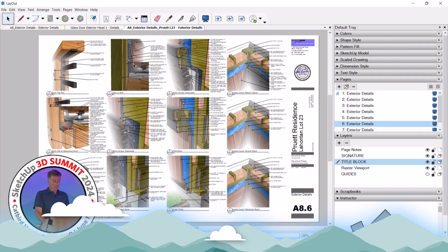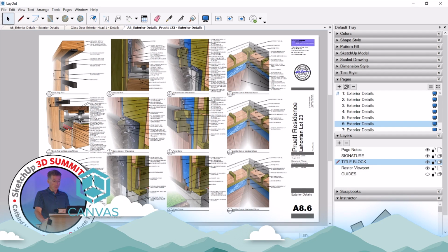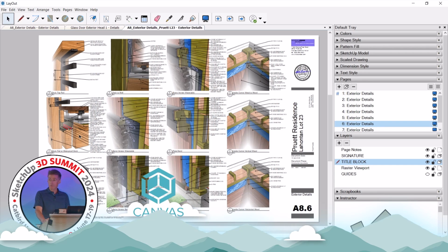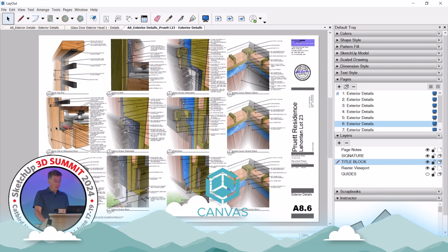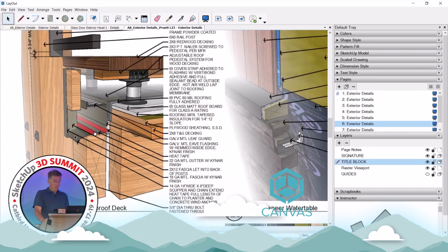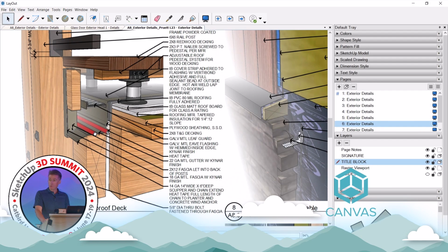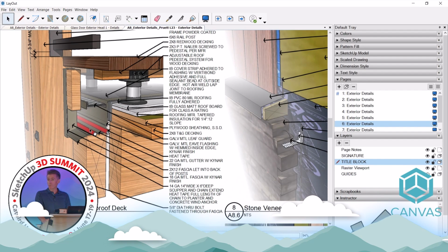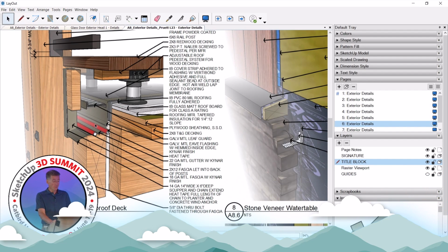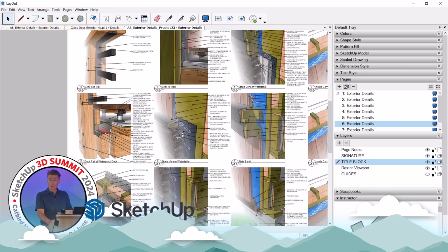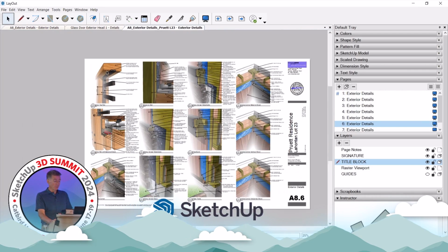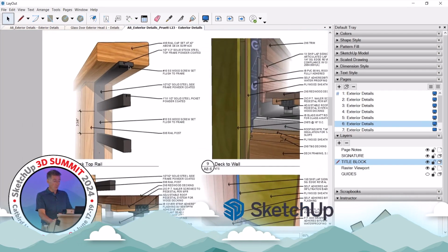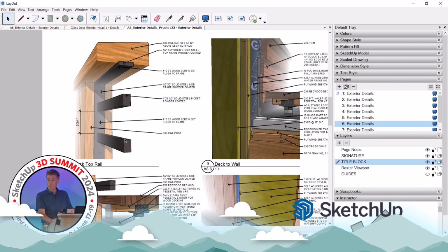different flashing at the deck. This is a pedestal deck system on top of the PVC where we have exposed timbers. And this is a concealed gutter that goes to an exposed scupper. And then this is a case where we do run heat tape in all of those, so we don't ever get it jammed up. And then a simple detail of the railing. It just shows the wood cap and then a welded steel frame.